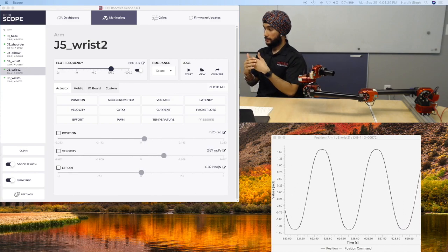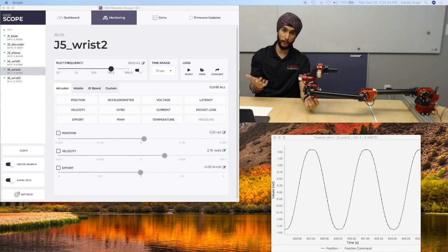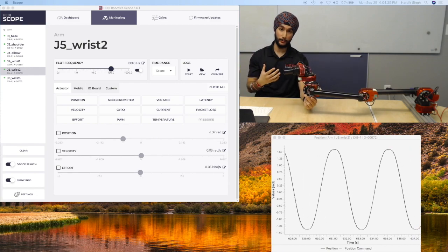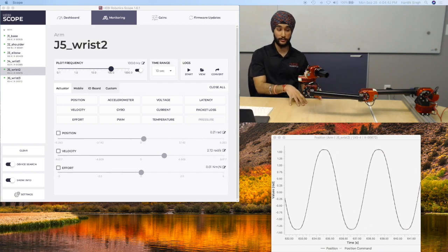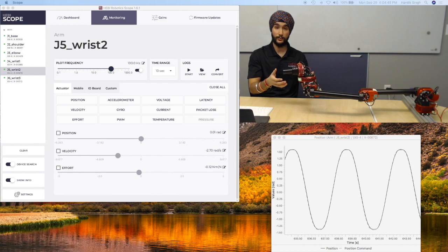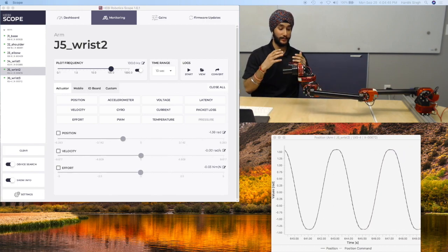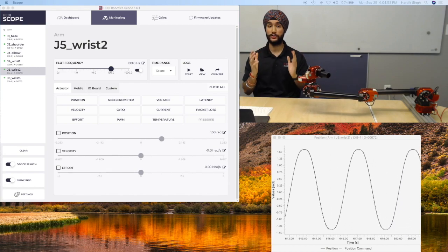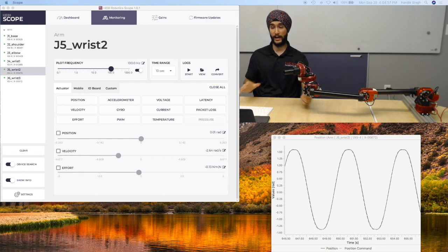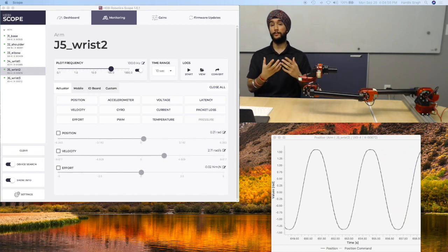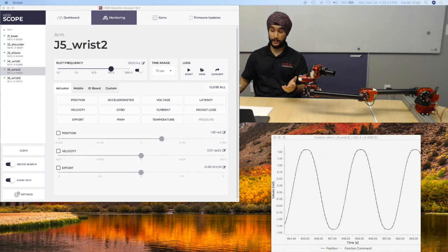So in this case, the control gains become a lot more powerful because they allow the actuator to actually follow the desired motion profile. That is invaluable when you're trying to get the motion control that you want. And the previous jerky motion without trajectories makes it possible for the hardware to either damage itself or damage the surroundings. Using this trajectory, we're in a lot more control of what we want to see, and the motions are a lot more predictable. Yes, it's a little bit of computational power, but the trade-off is that you get far better motion control.